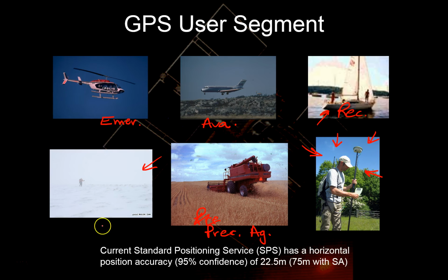Okay, which is you take a bulldozer or a grader. Let me just draw a crude bulldozer here. So here's our bulldozer with the blade and its tracks. And we're creating a road, and we want this to be exactly at a specific elevation. Well, let's just slap some GPS on this bulldozer, and it'll ensure that, pretty much within a single pass, it'll be able to follow exactly the elevation line that we want. That's generalized as machine control.